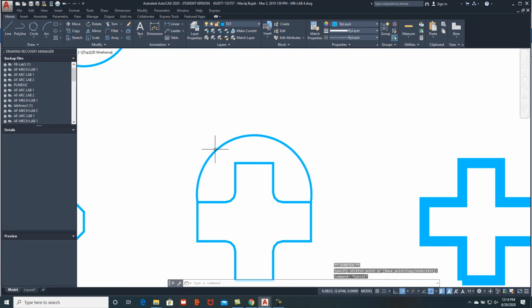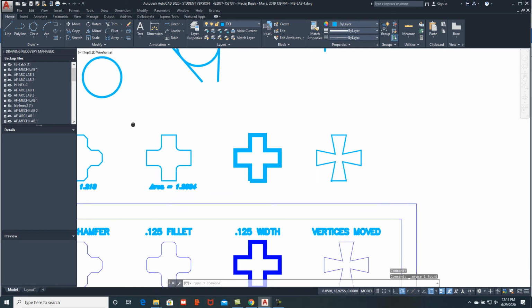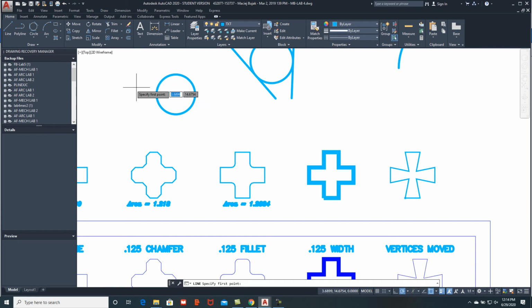I like the 3-point arc quite a bit. And then if I'm going to look at some of the other tools as far as radial geometry, oftentimes I'll draw a circle and then I'll trim it. I'll hit enter to make everything a cutting line, and then I'll trim off part of the circle, and that's how I'll construct arcs. I'll use circular geometry and then trim.